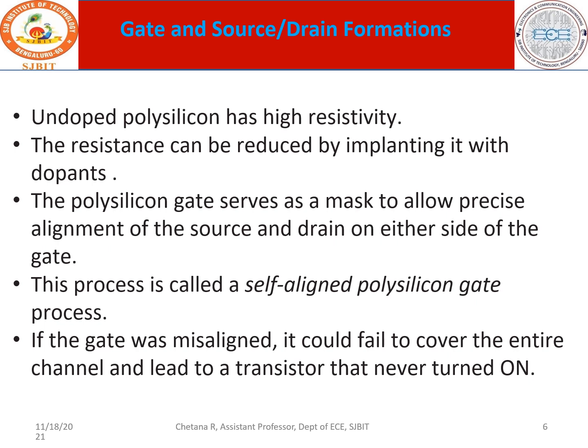So that region avoids the diffusion to be placed under the gate structure, and on either side only is it possible for the diffusion to have the dopings. This process by itself is a blessing in disguise, for it is providing the masking, therefore it is called the self-aligned polysilicon gate process.